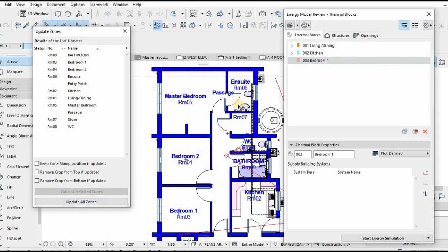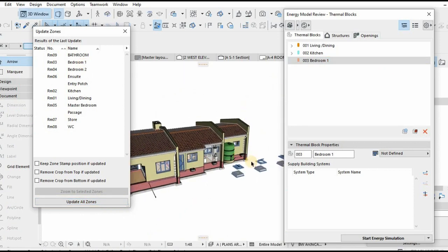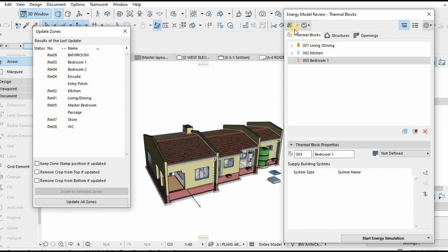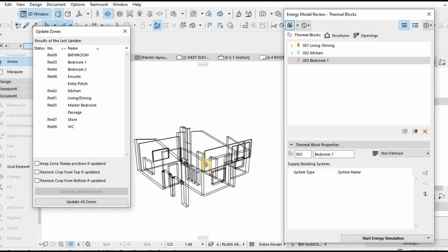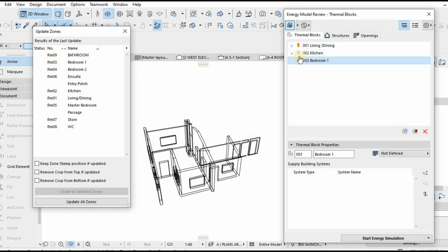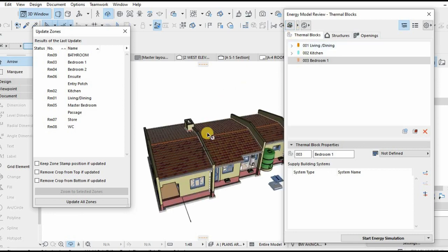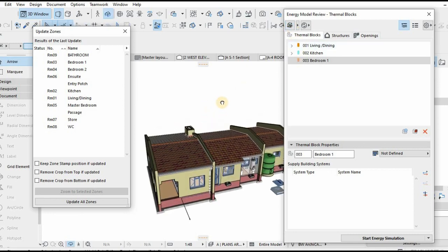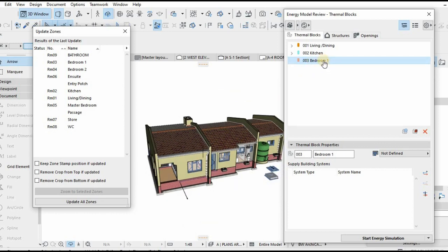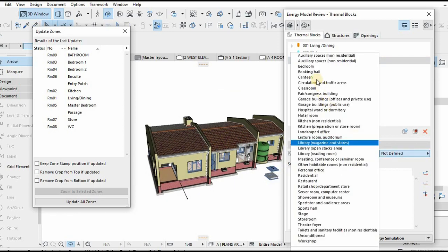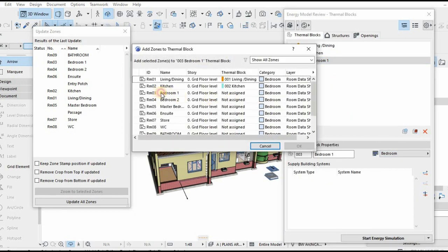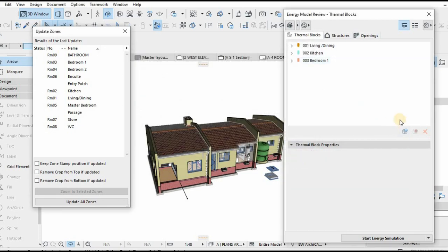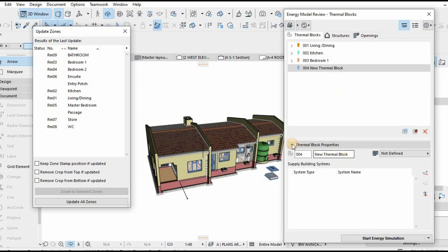Yes, it did. So I go back to 3D, to the energy model. You see, I started populating my energy model with zones, with the blocks I've created. That's the energy model, guys. Okay, building bedroom 1. You find the bedroom, and then you assign that zone to the block you created. It's all about that in the energy model.